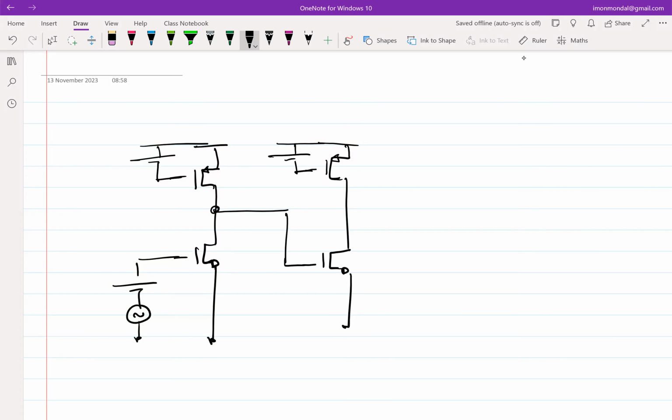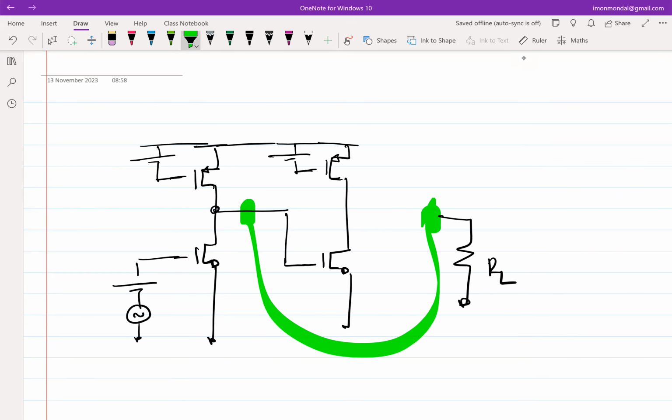For a differential amplifier, yes, we want a differential input, but that is not two stage, right? Differential input can be a single stage. Yeah, for high gain, right? So what was the reason why we couldn't get high gain? One of the reasons was if we had to drive a resistive load, and we connect this load directly to the output of the first stage, the gain will drop because the effective output impedance drops, right?